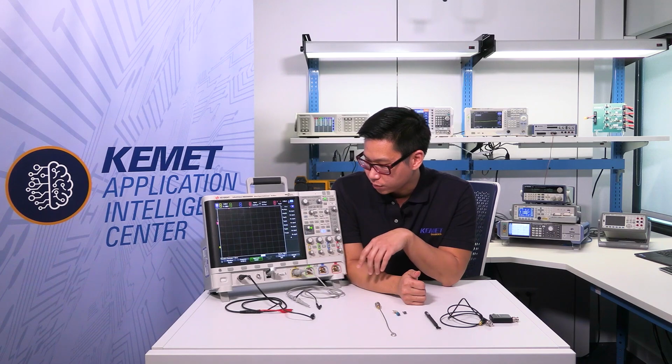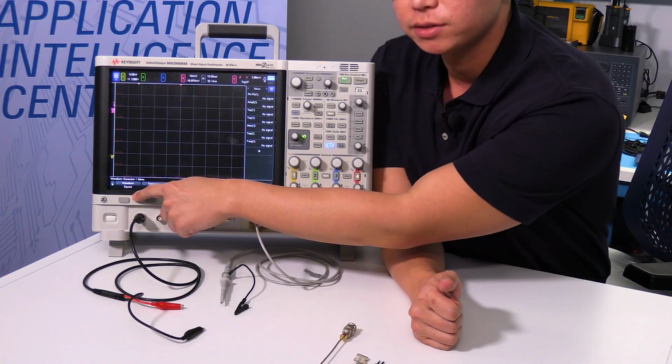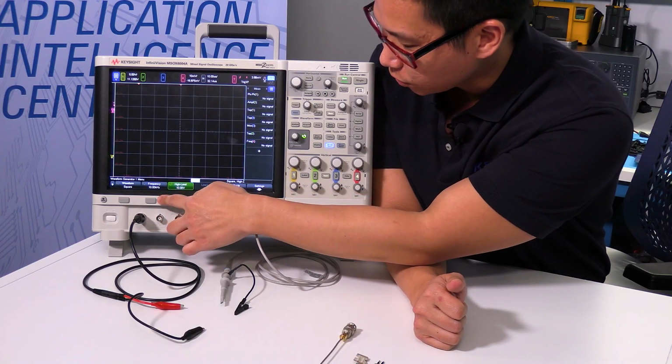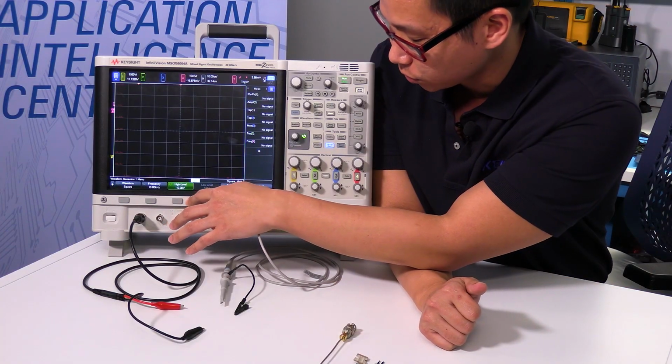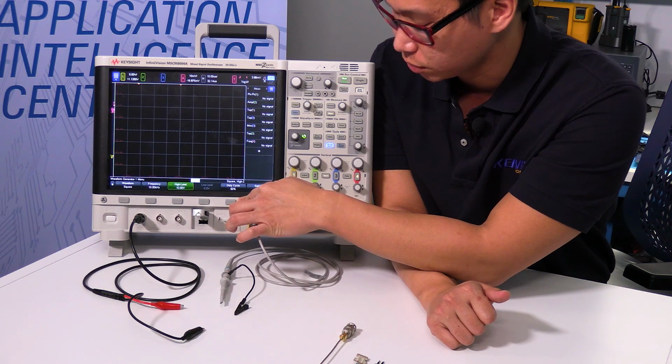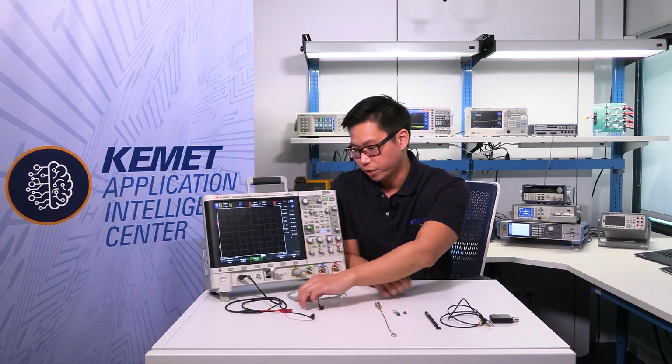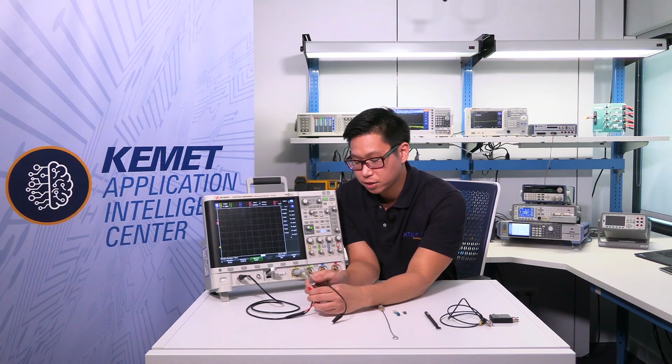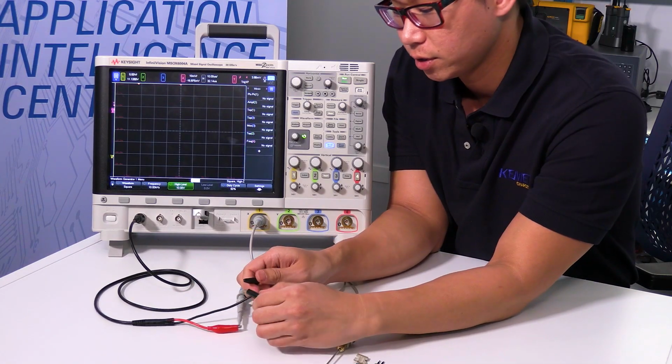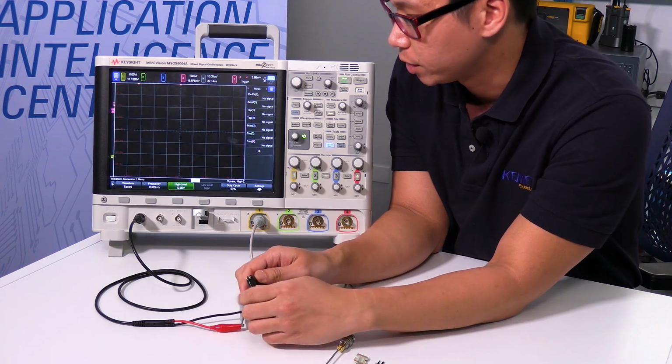All right, so first let's look over our function generator settings. So in our waveform settings, we're going to have a square wave output at a 10 kilohertz frequency with a 10 volt amplitude. So it's going to go from 0 to 10 volts, and we're going to set our duty cycle to 50%. So we can verify this by hooking up our leads to the oscilloscope, and we should see a square wave come out.